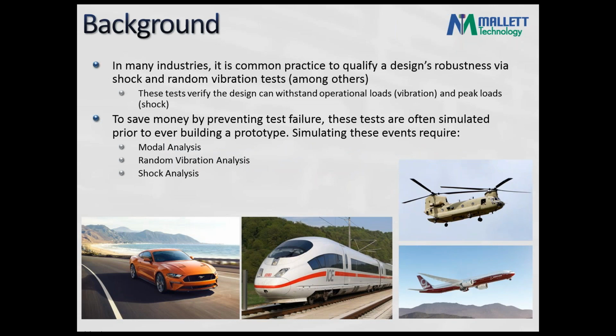So background to this, in pretty much, I'm not going to say all, but many industries require testing to random vibe levels and shock levels to qualify a system that it's robust enough to handle its operational life. Now, the caveat to this is, nowadays, especially when we have simulation, what we end up doing is simulating the shock and random vibration events prior to testing, because that allows us to do 2 things. One, identify any areas that are of concern or that show failure. And 2 is to redesign it, and so you can walk into testing with a much higher probability of passing without issue.